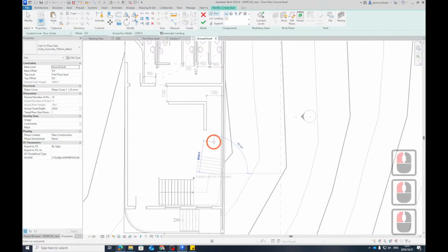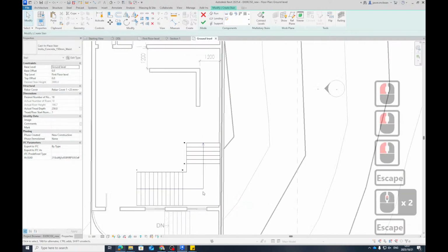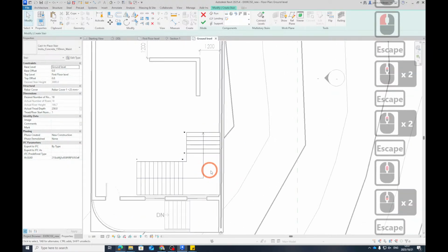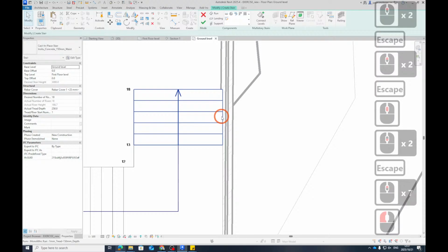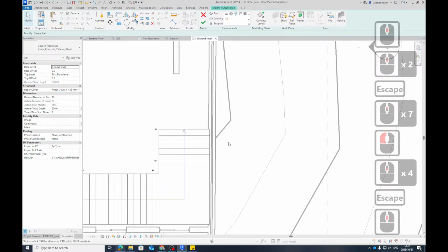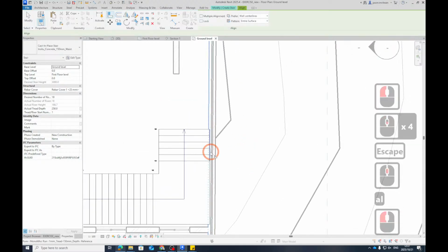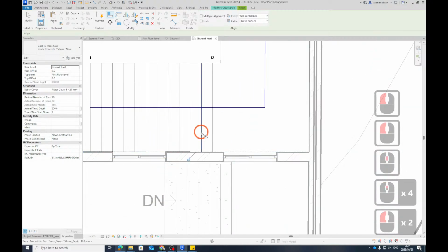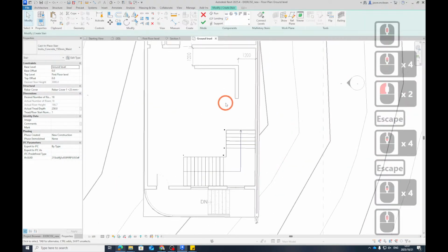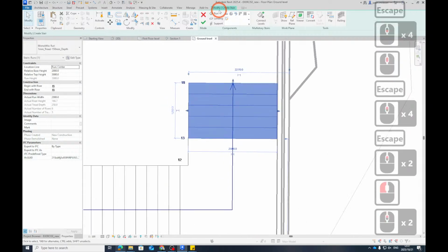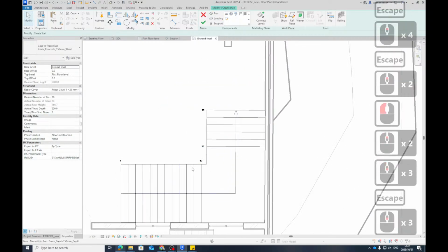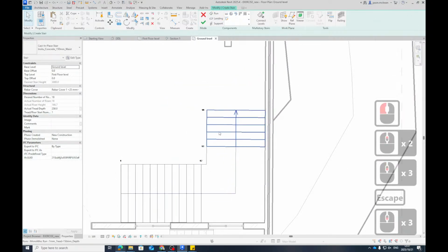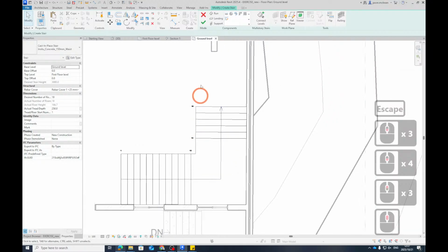Now I'll go in this direction because we're going around a corner. This doesn't matter. I'll explain now. We're going to sort this out in a minute. This is at a slight angle, so I might have to go align. See how I've aligned it to that? Align that to that. Because technically now your stair works correctly. Now this I can move back. You can draw the stair again to make sure you get the desired number, but for now I'm just explaining how to do this, okay?